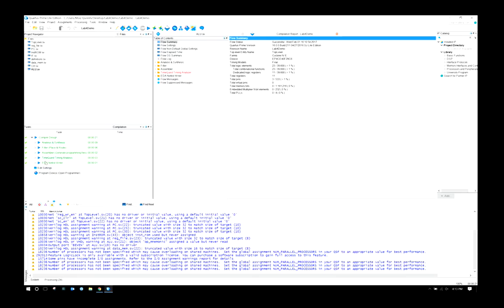And then for this class and for this lab, I think in the lab report they want you to show what Quartus produces for your module. So you're doing your ALU, you're doing your reg file, and you're doing your instruction fetch, IROM, PC. Those are the ones that you're making for this. And if you have a successful compilation, Quartus creates a netlist viewer. A netlist viewer is like the block diagram of that module.